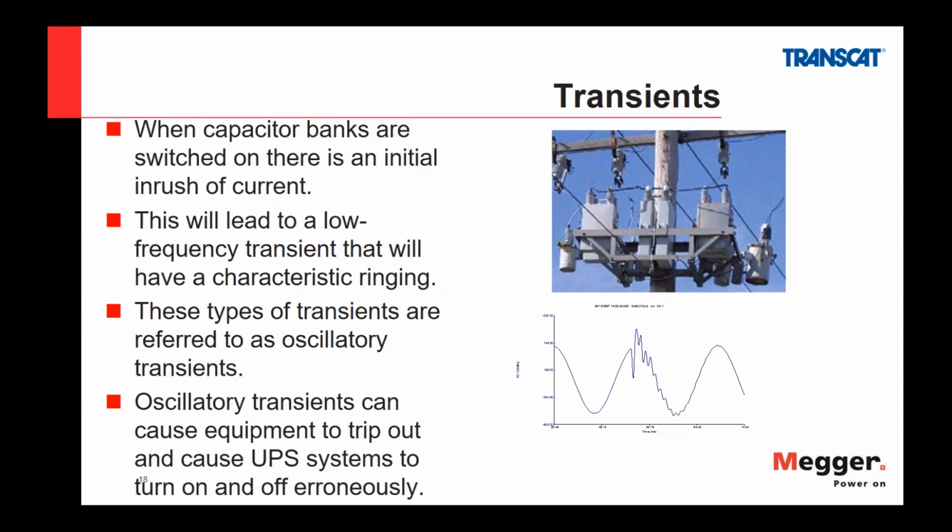Since UPS banks are made to switch quickly, if they are too sensitive, these transients will cause them to turn off and on multiple times per day. Typically, turning down the sensitivity on a UPS will fix this issue.